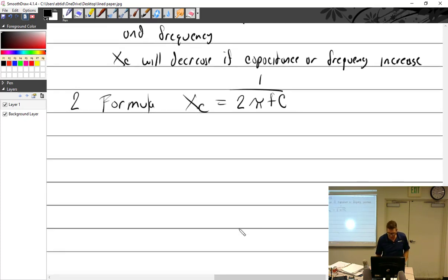All right, what would be the capacitive reactance? What is X of C if we have a frequency of 60 hertz and a capacitance of 100 microfarads? And get used to that, because farads are almost always going to come in a micro or a pico.